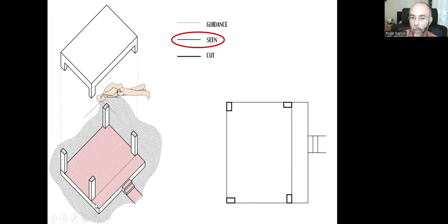And for the terrace, the size of this side is 1 meter. That is 100 centimeters. Again, in real world, I need to do the scaling, which I need to divide by 50 and find 2 centimeters for my drawing. And as you can see here, the terrace is the same size as the 6 meters here.